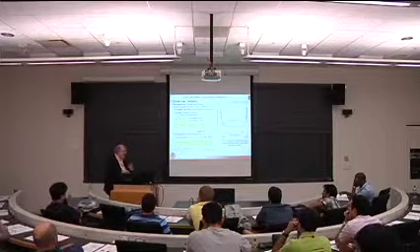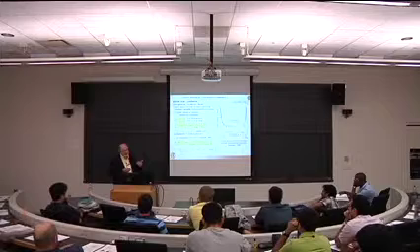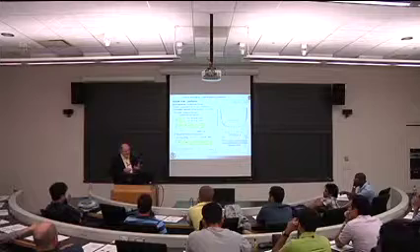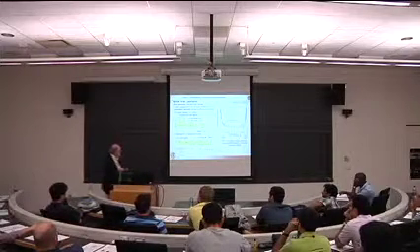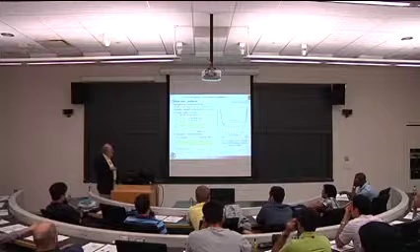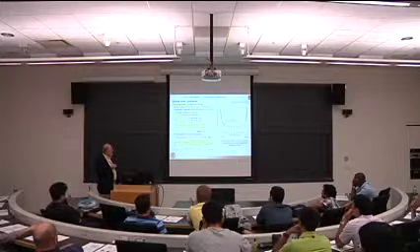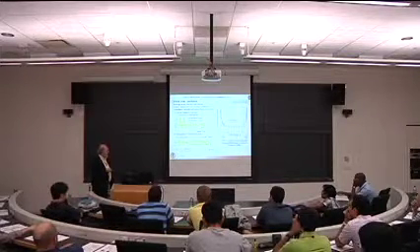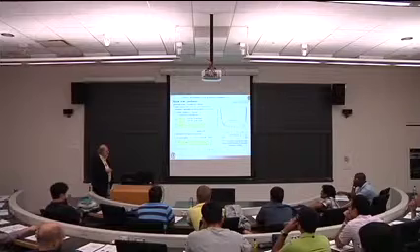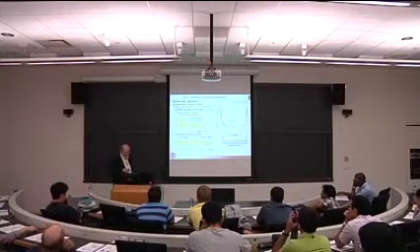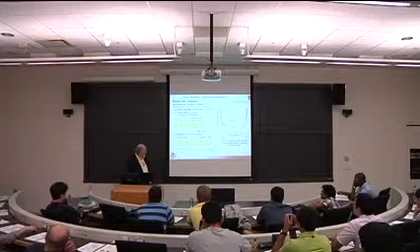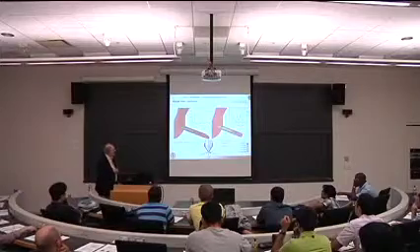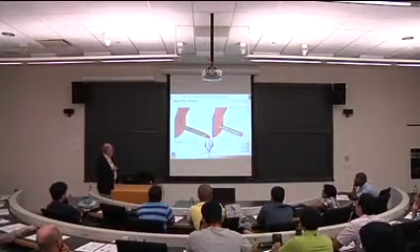And so the sound speed, which is dp/d rho, or in other words, the change in pressure associated with changes in density, becomes very low. So here's your sound speed equation. Knowing the sound speed variation with void fraction, we can calculate pressure as a function of density. So this equation here becomes your equation of state, if you like, to replace your ideal gas equation in your simulation.